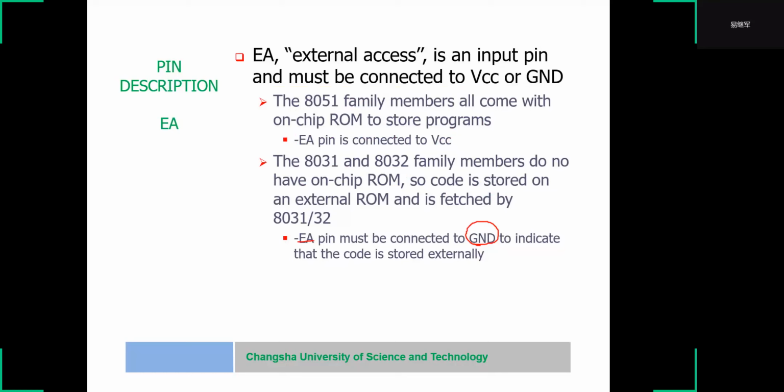Yeah, 8051. If you want to use the external ROM, and do not use the on-chip ROM, you connect the EA to the ground. Okay. Yeah.